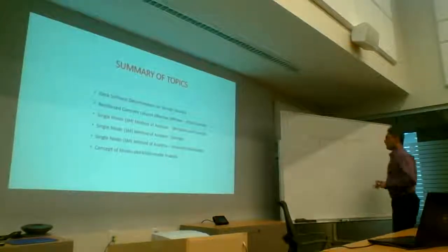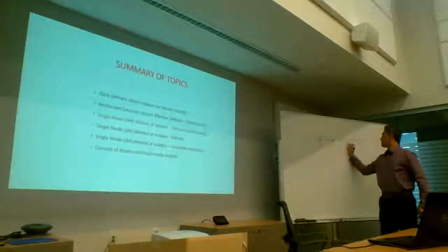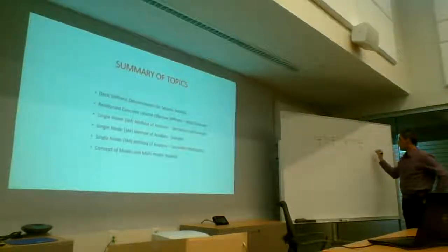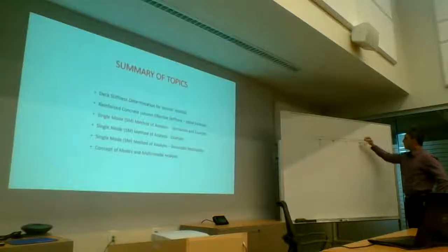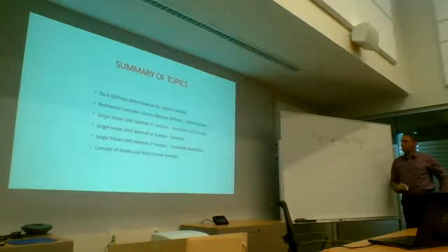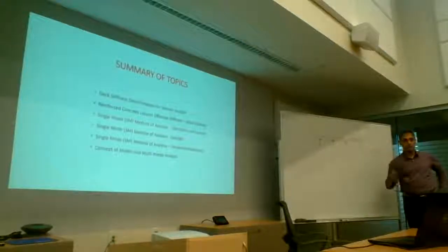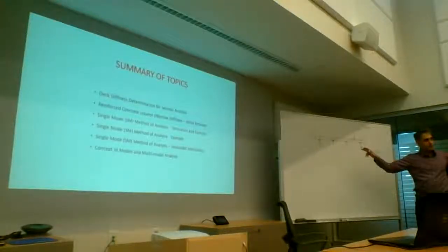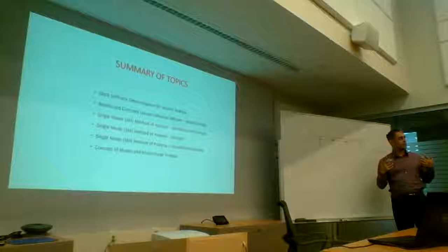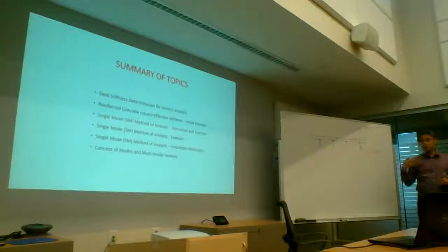Okay, so it looks something like that with your girders, and there may be a bit of a haunch here. You can think of these as, say, steel girders for this case, and a reinforced concrete deck. Now, a lot of people would do a full-on finite element analysis or finite element discretization of this and put that in their model, which, if you think about this, and if we say that reasonably speaking, this is going to act as a rigid diaphragm, there is no need to do that.